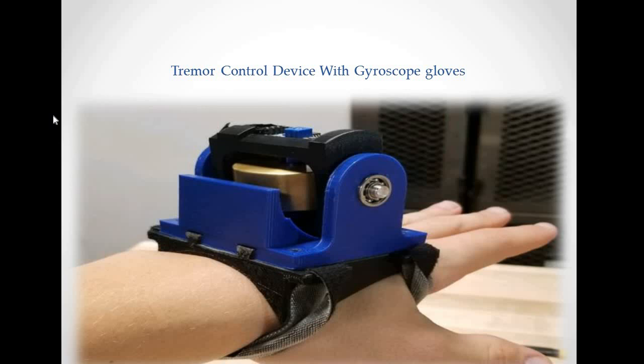So that the small tremor movements are resisted by the gyroscope force, yet allows for the intentional and deliberate movements to occur.